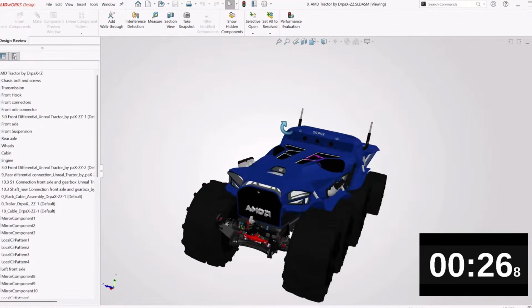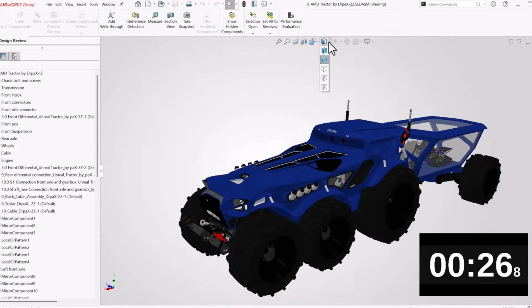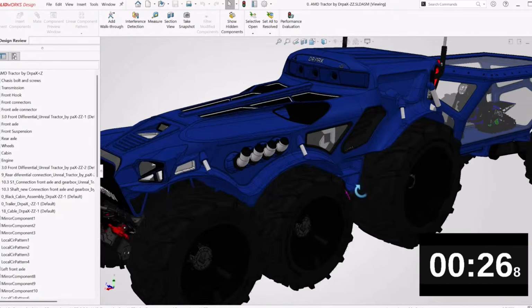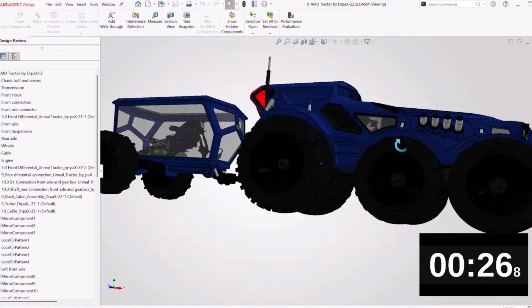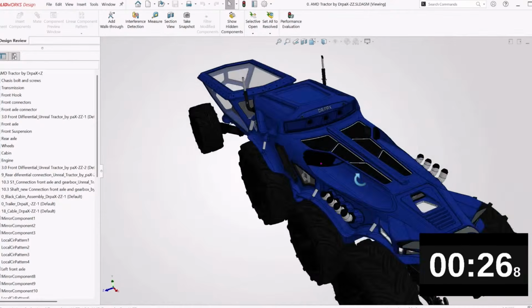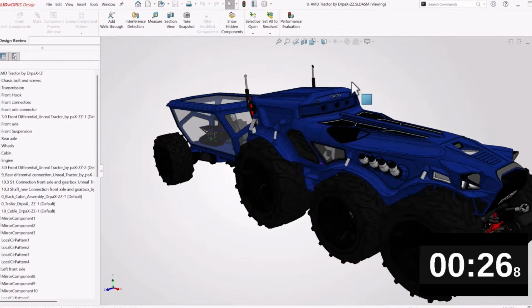This could be your default setting for how to open large drawings, but also make sure you choose it in your opening dialogues. When it opens, you can get a lot of functionality out of that large assembly through large design review, and then go from there to lightweight or to resolved.